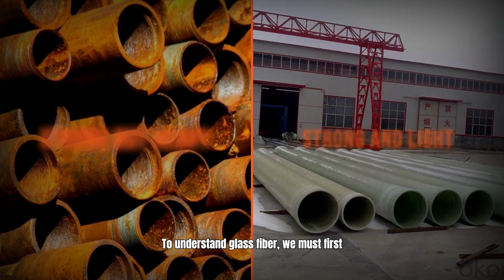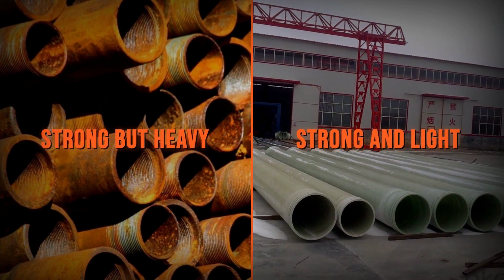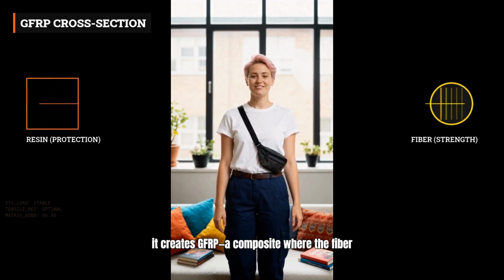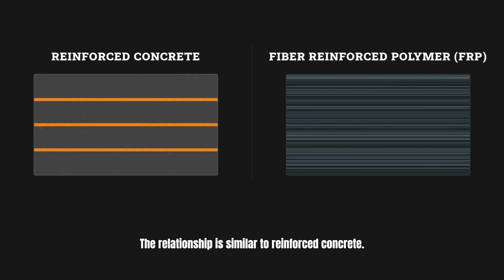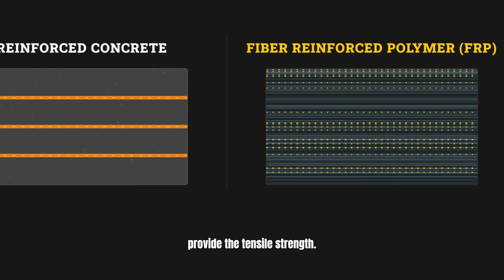To understand glass fiber, we must first understand the problem it solves: making structures strong, lightweight, and durable. When glass fiber is combined with resin, it creates GFRP, a composite where the fiber carries much of the tensile load. The relationship is similar to reinforced concrete. Resin holds the form, while glass fibers provide the tensile strength.